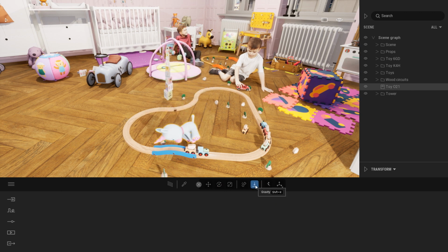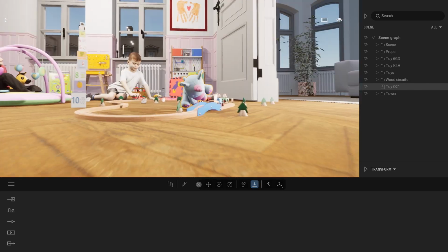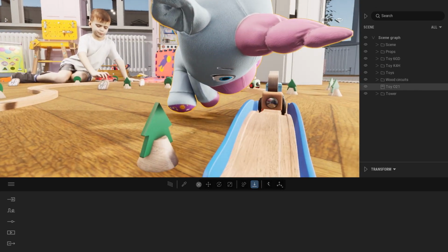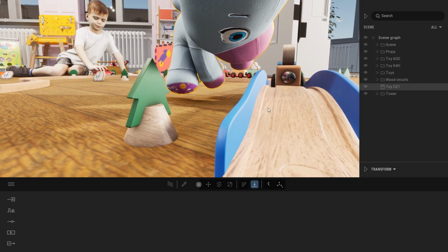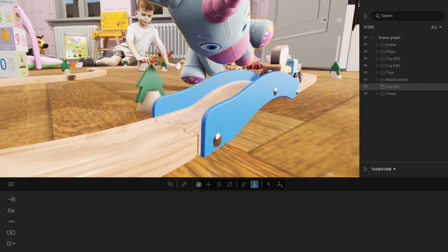With that new tool, we generate a simple convex bounding box around the object affected by physics, in order for gravity and collision to work in real time. For this reason, sometimes the contact points of the object are not perfect. So it's something that you can see when getting closer. For example, here, that object is actually not directly touching the geometry it is sitting on.